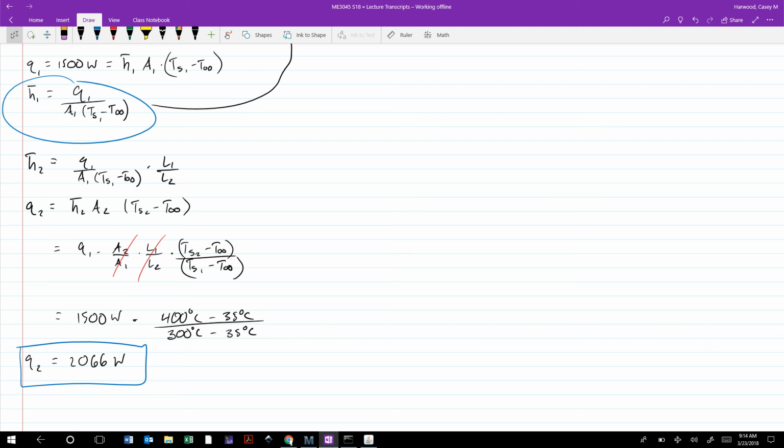We did this in fluids, where all you have to do is maintain similarity of those dimensionless parameters, and your dependent dimensionless parameter, in this case the Nusselt number, will also then be the same. And so once we knew the Nusselt number relative to another value, we were able to redimensionalize that to actually get h bar, and rescale the smaller blade to get a new heat transfer rate out.